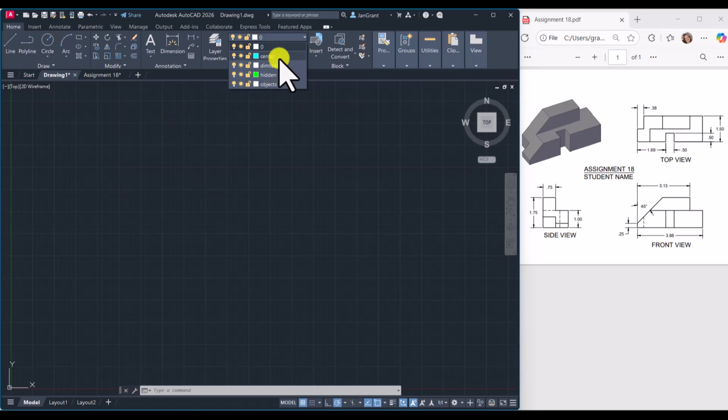All right. Now, like I said, you don't need the center layer. We just happen to have it because I used it in the template. And later on in the project, we looked at the command PURGE. If you ever wanted to purge out something that's not used, you can always type in PURGE and purge out the things that are unused. Okay. All right. So I need to save mine, but you go ahead and save yours to the file name that you need, and then we'll get started.